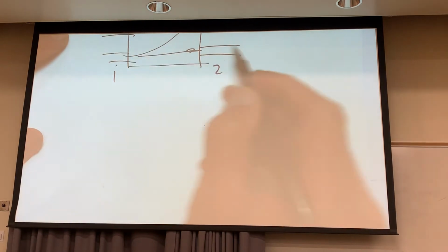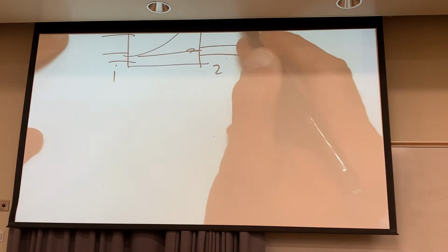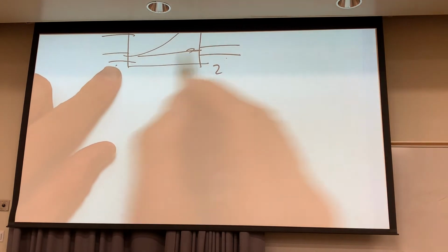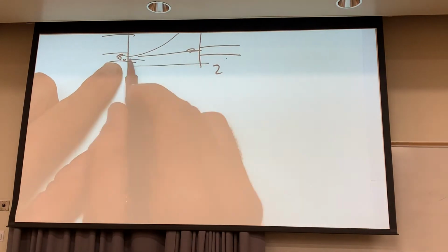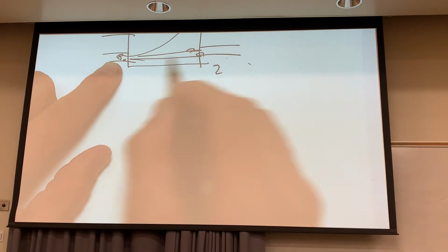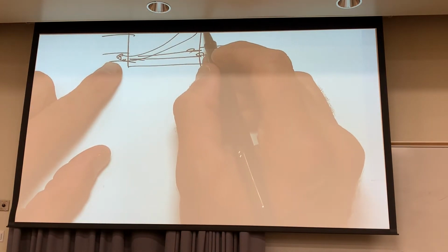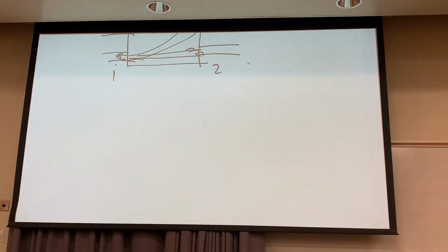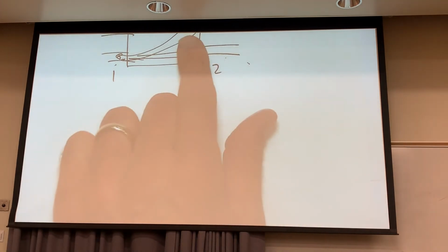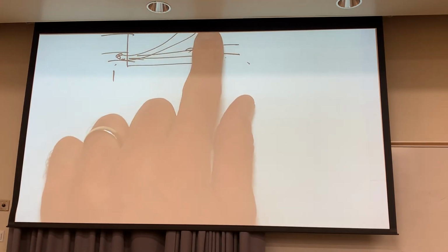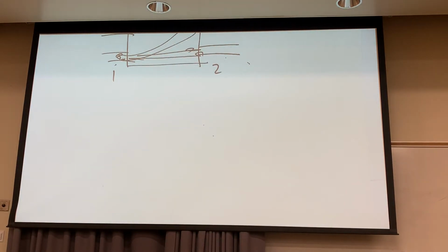It doesn't matter how the numbering is. Really, there's going to be 1, 4 on one side, 2, 3 on the other. It doesn't matter if the 2's up here and the 3's down here. But here's the idea. You want all the signal from port 1 to get to port 2. But you only want a small amount of that signal to get to port 3. And that's really for things like synchronization and stuff. So it might have maybe a 30 dB, maybe 40 dB of loss here. You don't want much signal going here, but you want enough signal there so they can do synchronization work and other stuff. You know what phase lock loops are? All right, well, anything that needs close synchronization, they can peel off some of that signal.